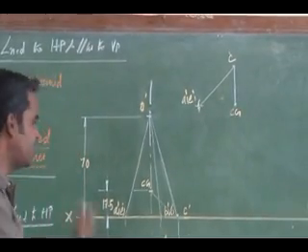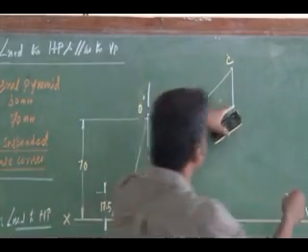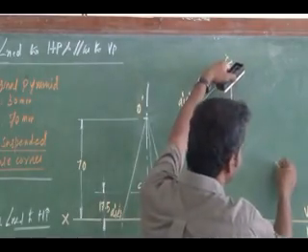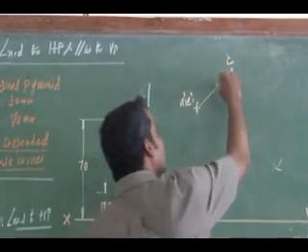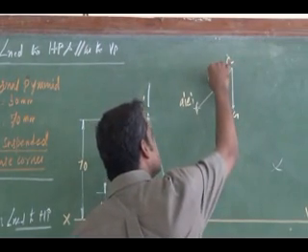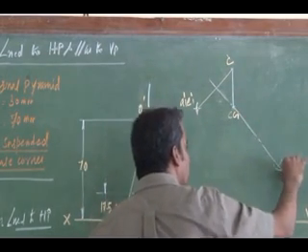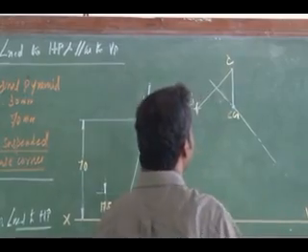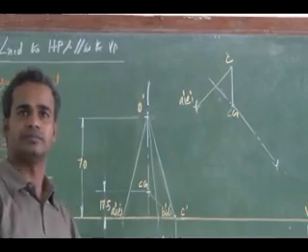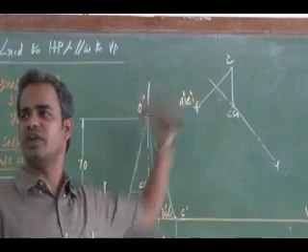Similarly, I can get my apex from the previous. What is the distance from CG to apex, or from C to apex? I can measure that. Otherwise, the line along the CG, perpendicular to this base, is going to be my axis, and on this axis I have to get my apex. So here, just redrawing, you need the two known locations to reproduce the front view.